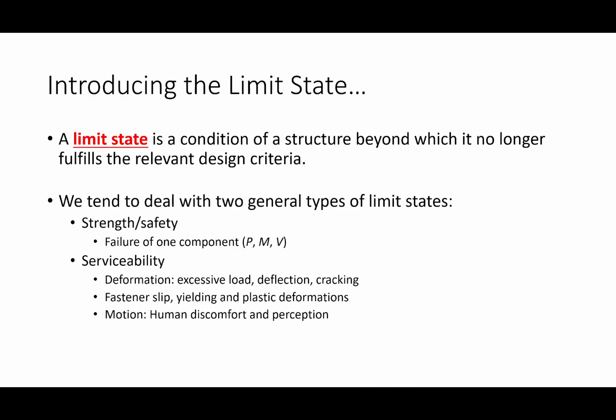Well, think about a truss, right? So trusses have tension members and compression members, but why would we design them differently? Well, compression members like to do this thing called buckling, and tension members don't. So the mechanics are different, and so because of that, we have to handle that a little bit differently. Things under bending don't behave the same as they do under shear and whatnot. All right, so strength limit state is one class of limit states.